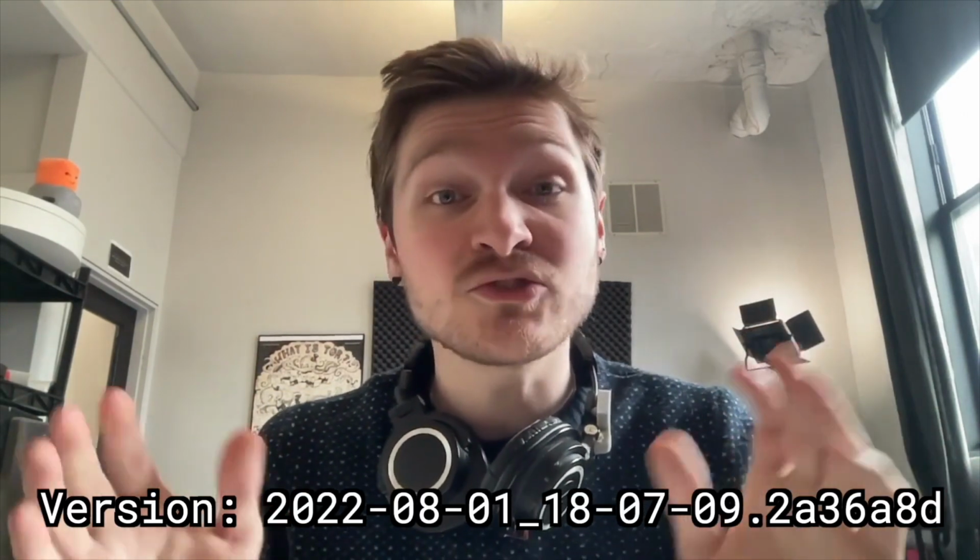You might find that when you open OpenPnP, it throws some error about something that it's not able to find in your configuration. If you find this, make sure that you are using the config that's in the v3.0.2 release, and also that you're using this version of OpenPnP because these two are known to work together.